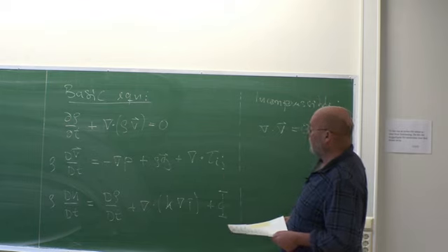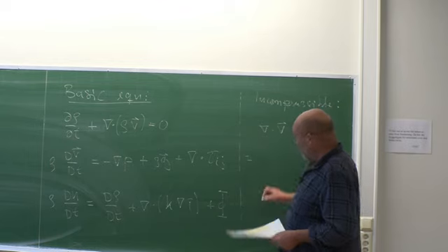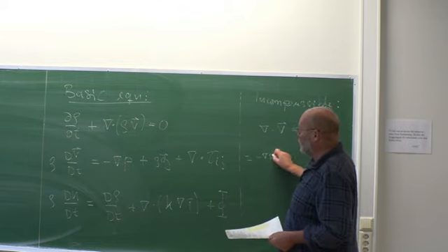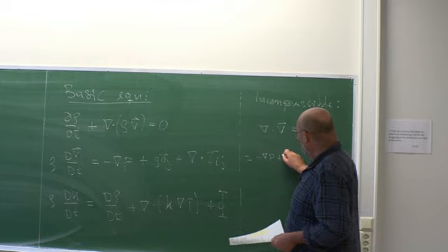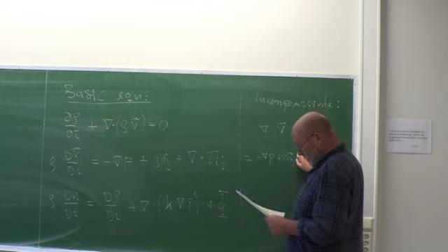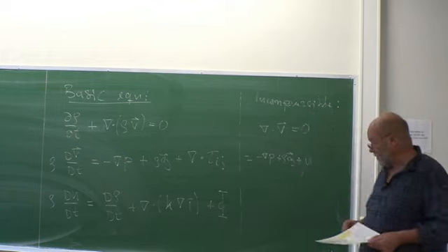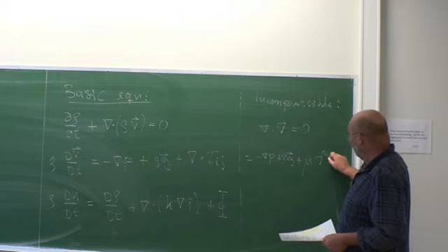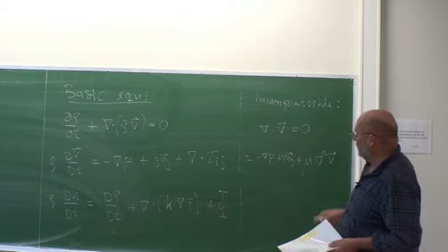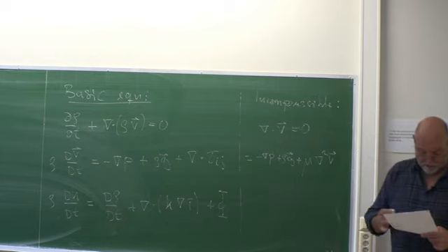The left-hand side is going to be the same. And here, well, we also have the pressure and gravity. But then here you will typically do the following: you put the viscosity on the outside, and then you'll have the double derivative of the velocity field. So it simplifies a lot.